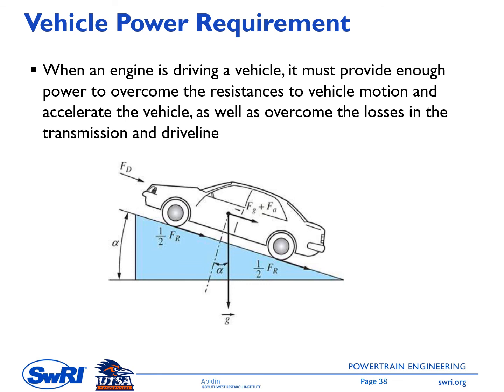This is the schematic of the forces acting on a car while it is climbing a grade. We have an aerodynamic drag here, and then there is an inertial force in case we need to accelerate this car. And because this car is climbing a grade, there will be a gravitational force as well. And there is also a friction. This is a rolling friction through the wheel, so Fr. This means that the engine power should overcome all of these forces.